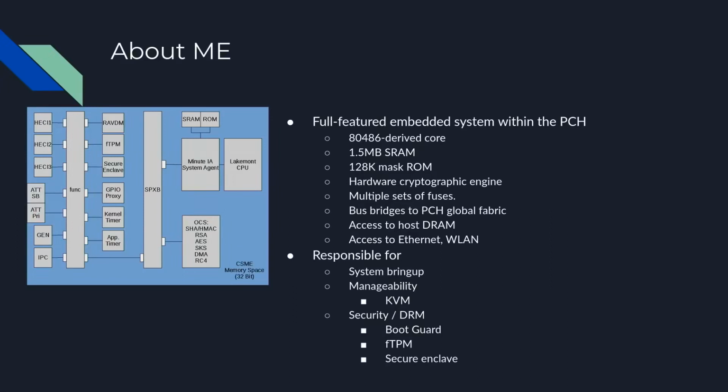And its tasks nowadays include starting the computer, as well as adding management features. This is mostly used on servers where it can serve as a board management controller, do remote keyboard and video. And it does security, bootguard, which is the signing of a firmware and verification of those signatures. It implements a firmware TPM. And there's also an SDK to use it as a general purpose secure enclave.